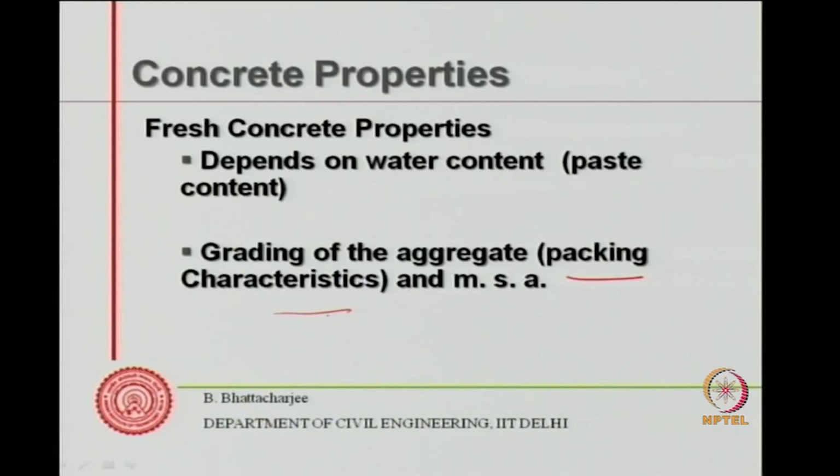That's a very important issue. So grading of aggregate, and we have also seen, as I increase the maximum size of aggregate or number of sizes, my packing density improves or the void system in the aggregate improves. So good grading, higher MSA, they will always reduce down the void system in the aggregate, and therefore my paste content required for appropriate moldability or workability would be less. So it will make the concrete economic.